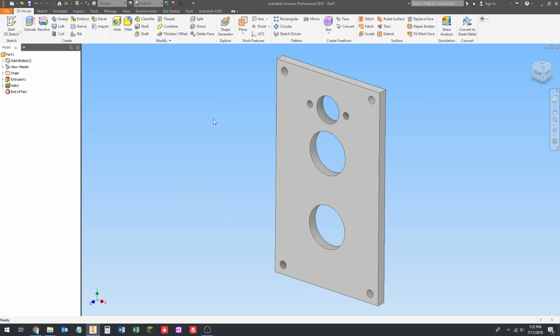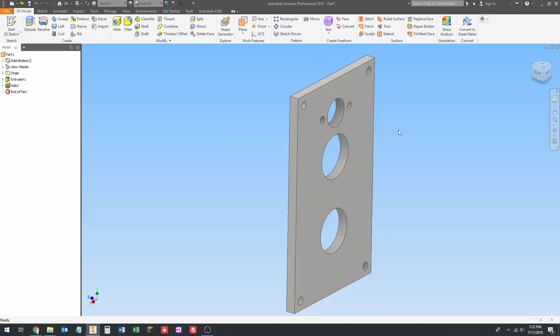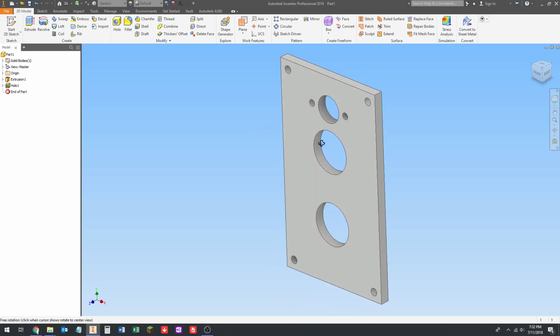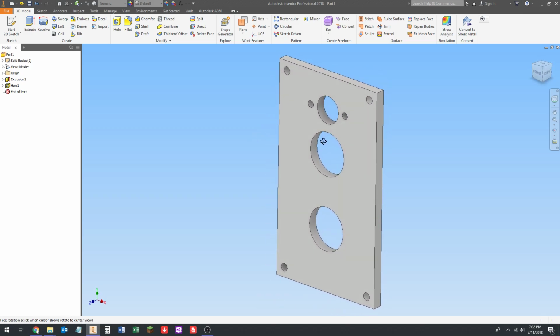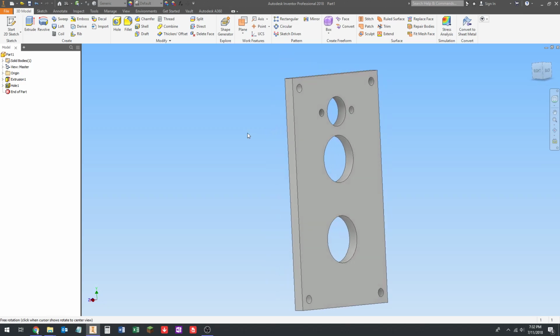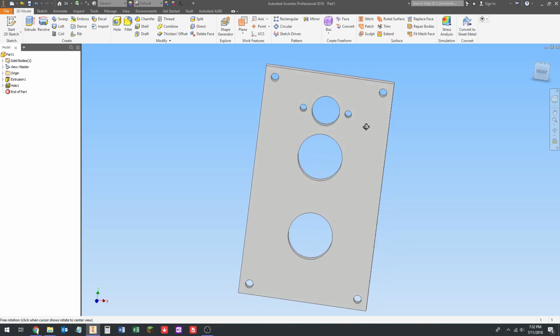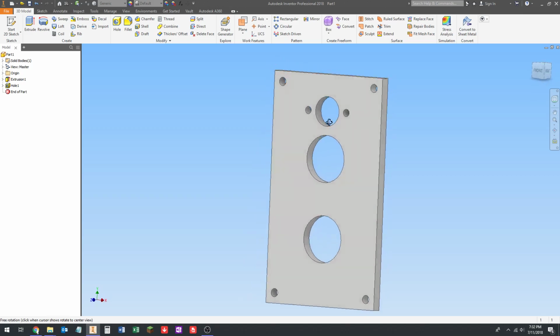This motor has vents on it, and the vents are on the face of the motor, the front of the motor. So we're going to attach the face of the motor to this plate, and it's going to be squashed up against this plate. And there are holes there that pull air in that cool the motor. So if we just bolt the motor up to this plate like we are here, air won't be able to get into the motor, and the motor will get hotter quickly, and the motor could burn out.